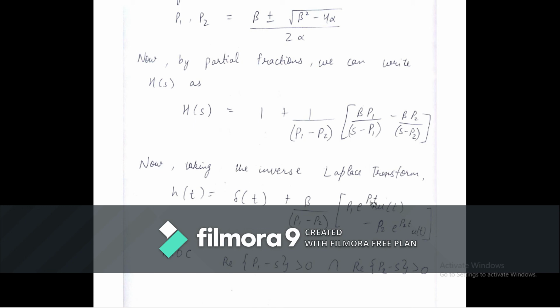Now we will find our region of convergence. For the region of convergence, this part should be greater than 0 and this part also should be greater than 0. So we will take the intersection and we will get our region of convergence. And this was our filter 2.